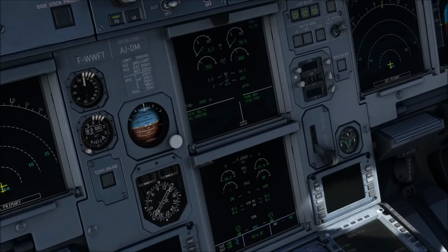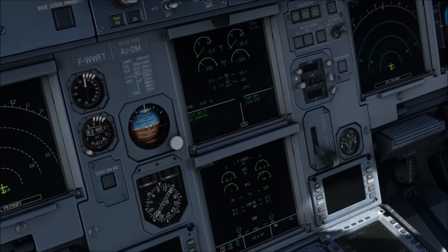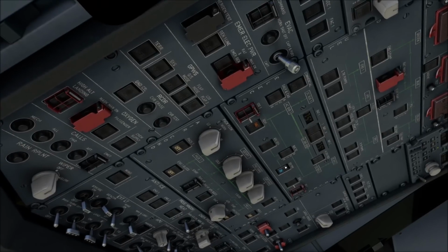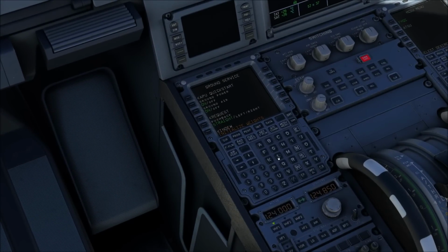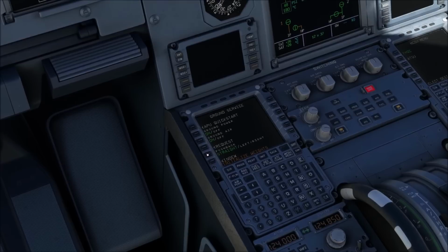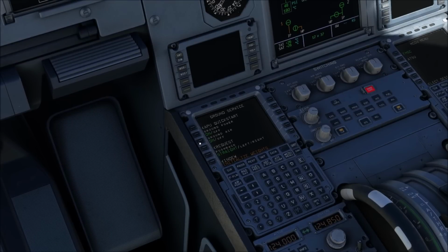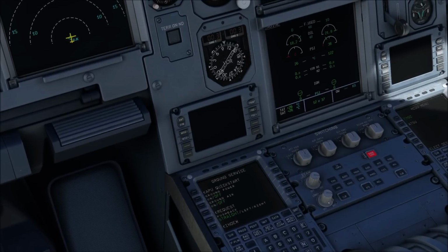Okay, after engine 2 is started, we are going to deselect the external power, like here, off, and then request external power disconnection. There is a warning there: disconnecting the external power with the external power push button set to on may cause injury to the ground engineer. Request disconnection of the external power only when the external power push button is set to avail. Okay, so that's the case now, and we can go ahead and disconnect external power and external air, like so. We don't need all of those ECAMs, we can ignore them for now.